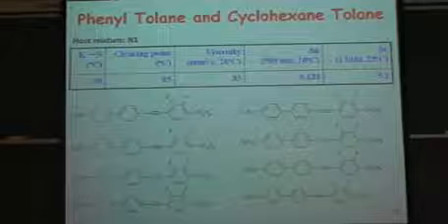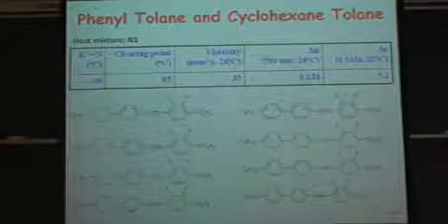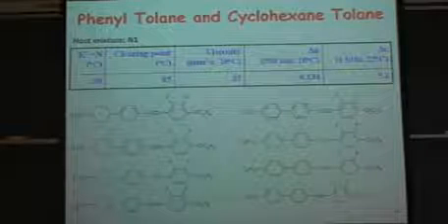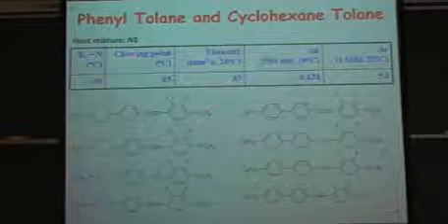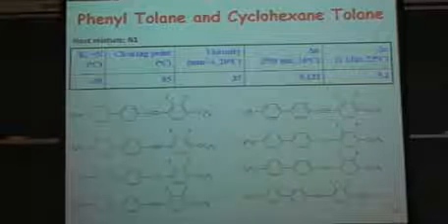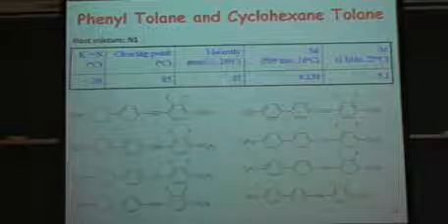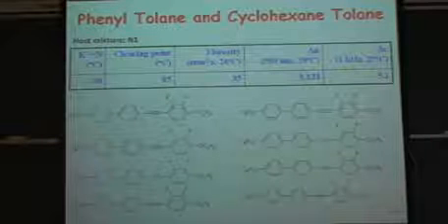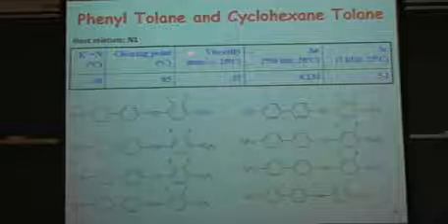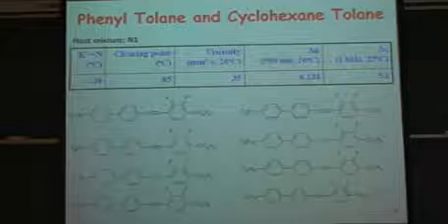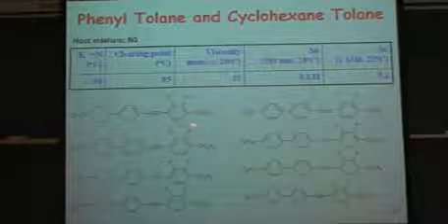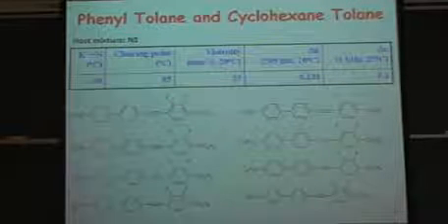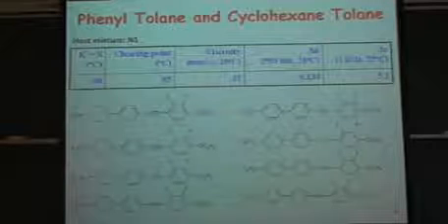But all the materials have a very high melting point, so it's difficult to measure them directly. So we choose the guest-host method. We choose a host. It is either a commercialized liquid crystal or mixture, where you already know all the properties. So usually we choose a host mixture in which the guest compound has good solubility, and also the host mixture should have similar physical properties.